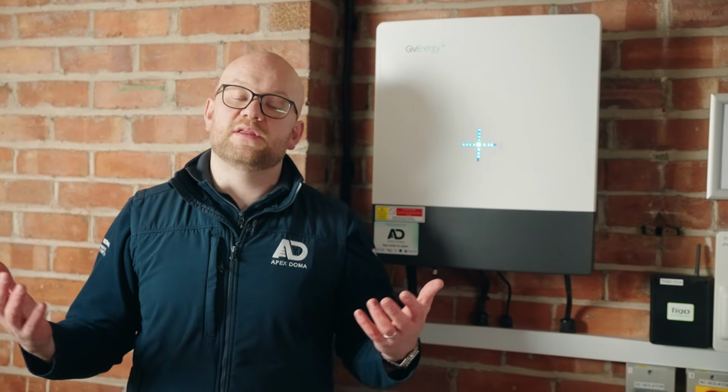If you think about it, we've got 100 kilos worth of the lithium iron phosphate battery. We don't want that to be installed anywhere where it could impede your exit in the event that you have a house fire. Now, at this point in time, you might think, oh, is it going to cause me a big fire? No, lithium iron phosphate batteries by nature are very safe. They're not the same type of battery chemistry you'll be familiar with like e-scooters or e-cigarettes, for example, where you see these big flames happening.